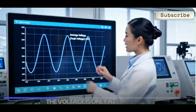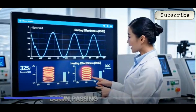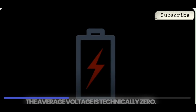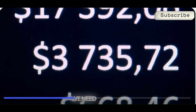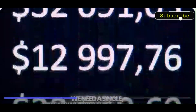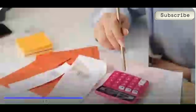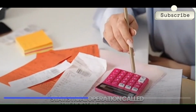The voltage is only at that peak for an infinitesimal instant before dropping back down, passing through zero and reversing polarity. The average voltage is technically zero, but the average power is certainly not. The bulb gets hot. We need a single, steady number that represents the heating effectiveness of this constantly changing wave. To find this effective value, we use a statistical operation called the root mean square.